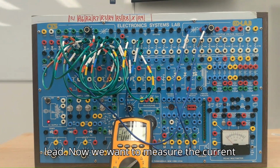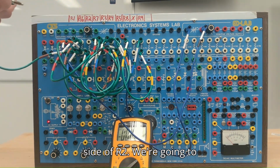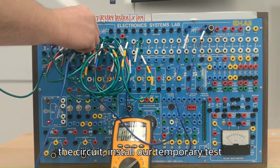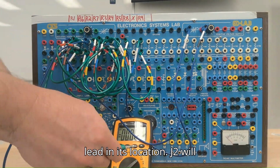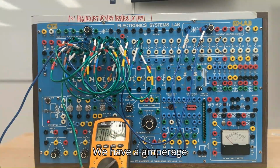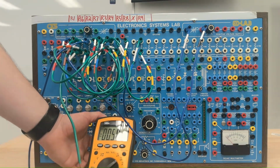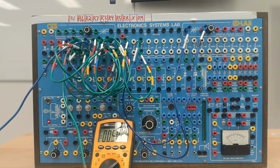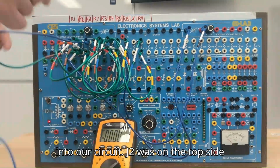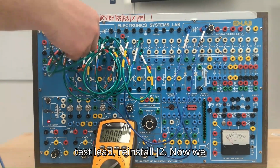Now we want to measure the current through J2. J2 is on the top side of R2. We're going to remove J2 from the circuit, install our temporary test lead in its location. J2 will go into the common port of the meter. We have an amperage reading of 0.5 milliamps. We're going to reinstall J2 back into our circuit. J2 was on the top side of R2. Remove that temporary test lead, reinstall J2.